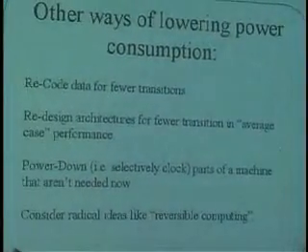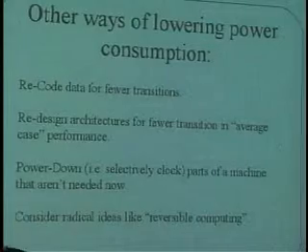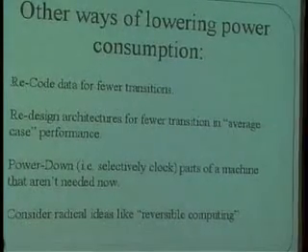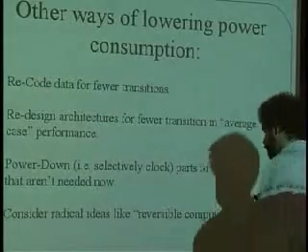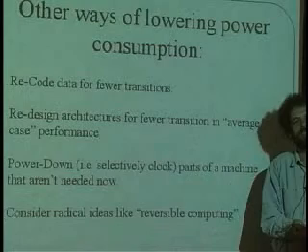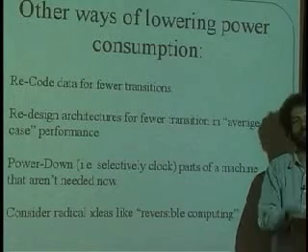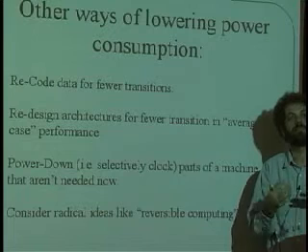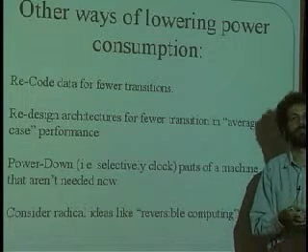Okay. So we keep trying to make our power lower and lower. How do we get rid of all this terrible power consumption? The one thing that I think you've all learned now is that the stuff that really eats up power is transitioning these capacitors from low to high and from high to low. So what if we changed our computer to minimize the number of transitions that are being made?